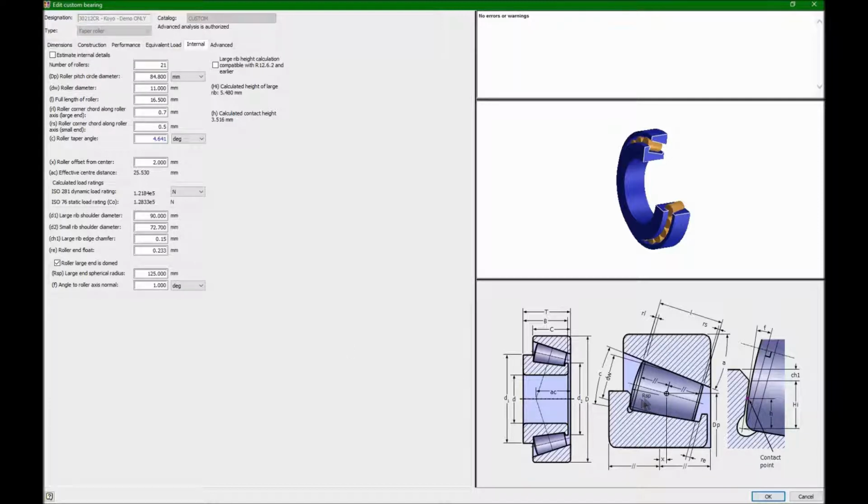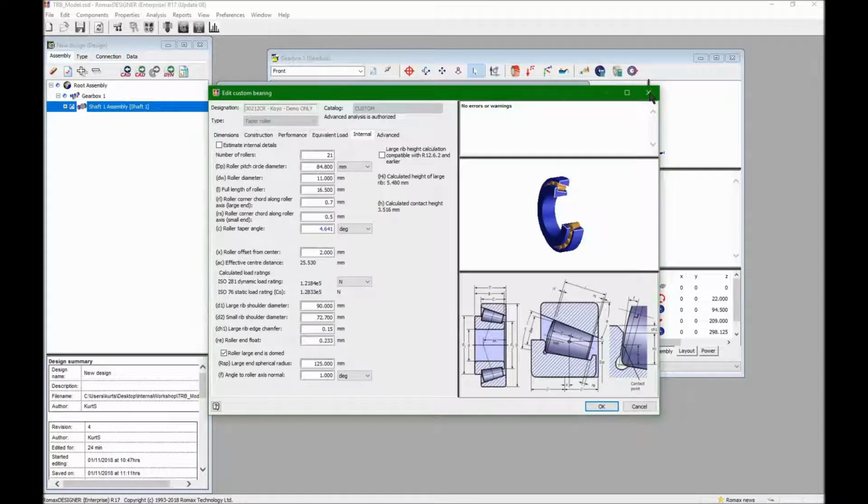In this picture, you can see RSP, the roller spherical radius, is this surface, and the angle F over here, perpendicular to the roller's axis of rotation to the theoretical sharp corner, the rib angle, is given as F. So we're going to modify these two values.